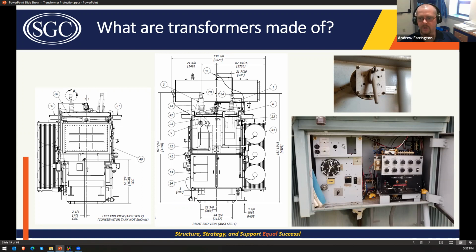So we want to operate around neutral, but also there are maintenance reasons. I'm not super familiar with this, but I've been told there are maintenance reasons why you want to exercise that mechanism that changes from raise to lower, and it can prevent malfunctions of the LTC. So they try to make it so that the low side is operating around neutral. Looks like they did a pretty good job here.